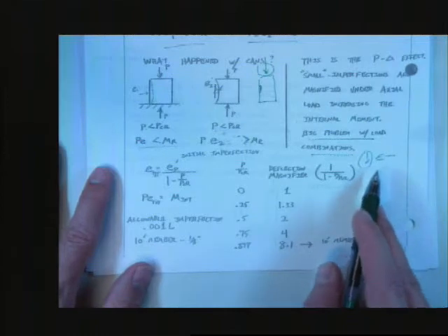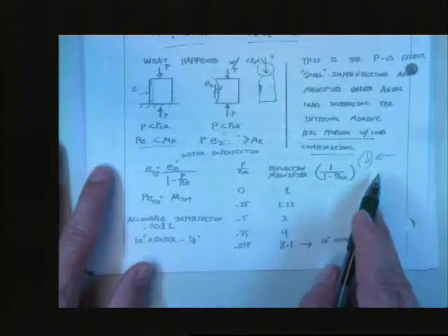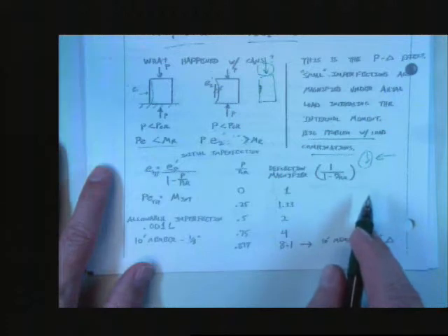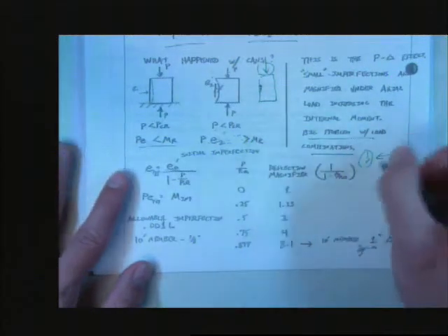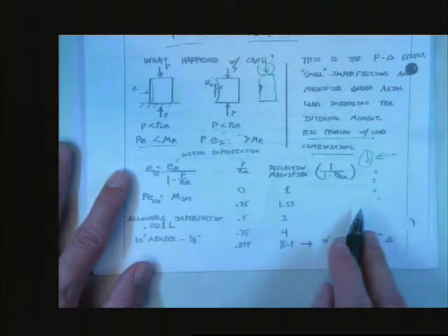So oftentimes, I can't speak for all states, but I can speak for the state of Texas, what actually controlled our design on columns with roadways underneath was an 18-wheeler impact, horizontal impact. Okay? Wasn't anything to do with gravity loads. All right? And you put these things called bollards or whatever, or all kinds of things in front of them, they will find a way around them.